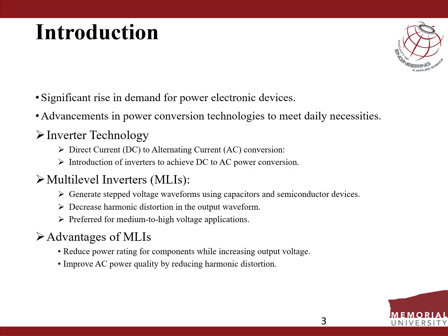Multi-level inverter technology works by connecting capacitors and semiconductor devices in series with one or more DC sources to generate stepped voltage output waveforms. These waveforms closely resemble the ideal AC waveform, reducing the harmonic distortions and improving power quality.